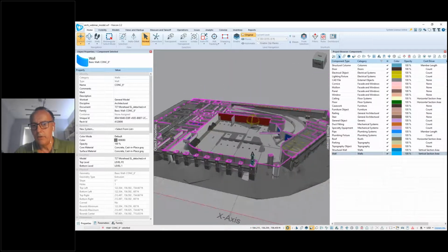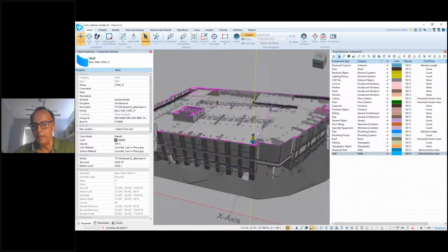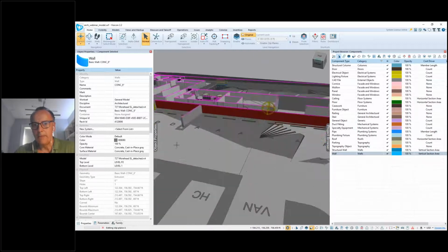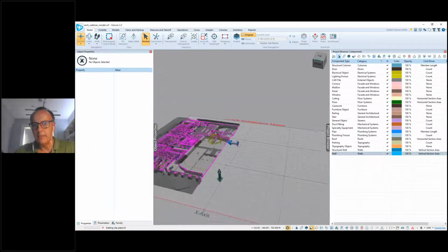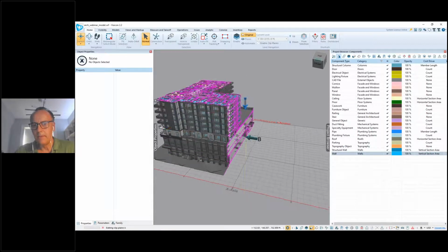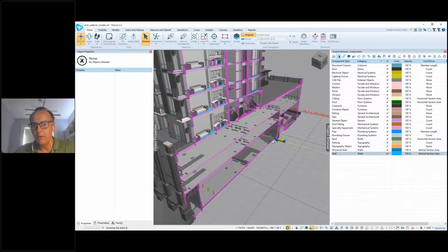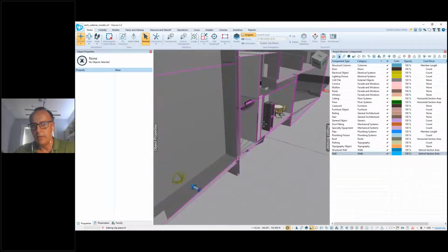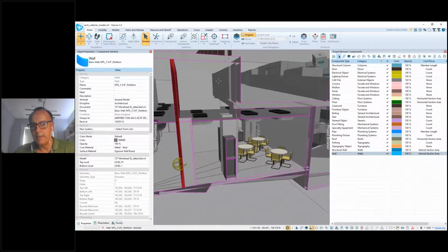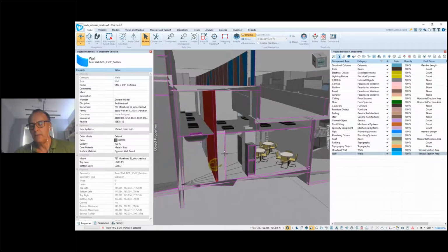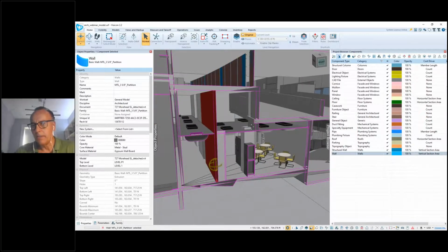And then really you're using these various clip planes. So here, this is a clip plane that way. If I want to cut another section here, I select the front of this wall, add a second clip plane. So you can add up to 9 clip planes per view and combine those, right? So this gives you a nice view or section of the structure if you're trying to figure out, for example, how your structural system will interface, let's say, in this mezzanine area with a double height ceiling, right? So this allows you to very quickly go in and explore even the architect's model.